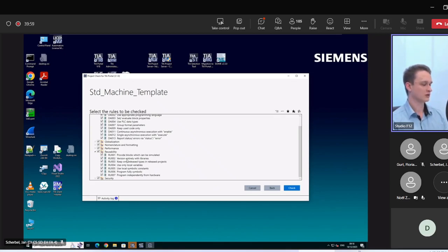You should take into account some rules when it comes to the reusability. So, of course, the versioning, we talk about this topic later on, of the different contents should be done in the libraries. So we also provide a versioning which comes in the library solution. And that's, of course, very important to have. And also, symbolic programming is an important role to make the program code on the one hand side reusable, but also maintain a very high readability.